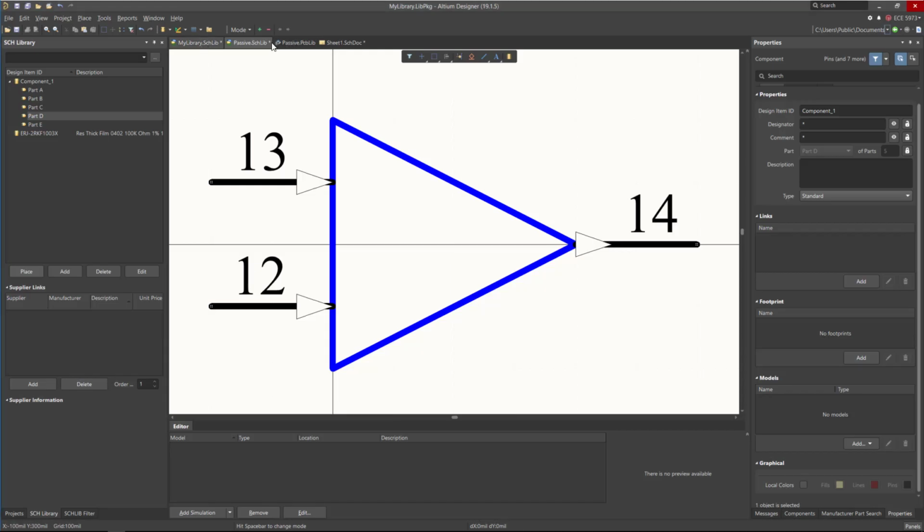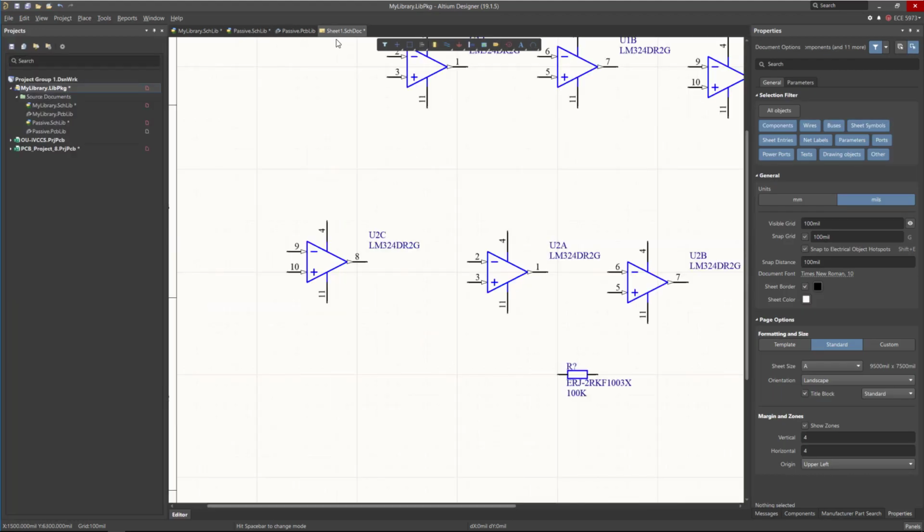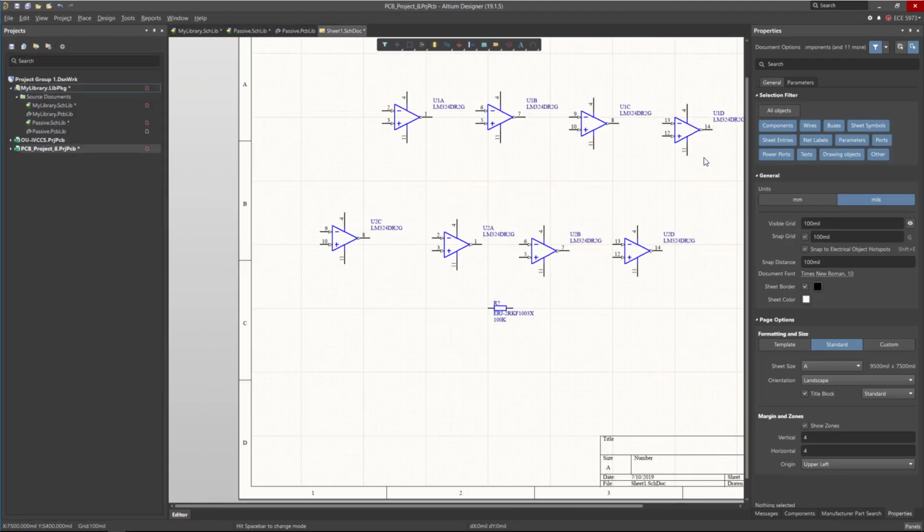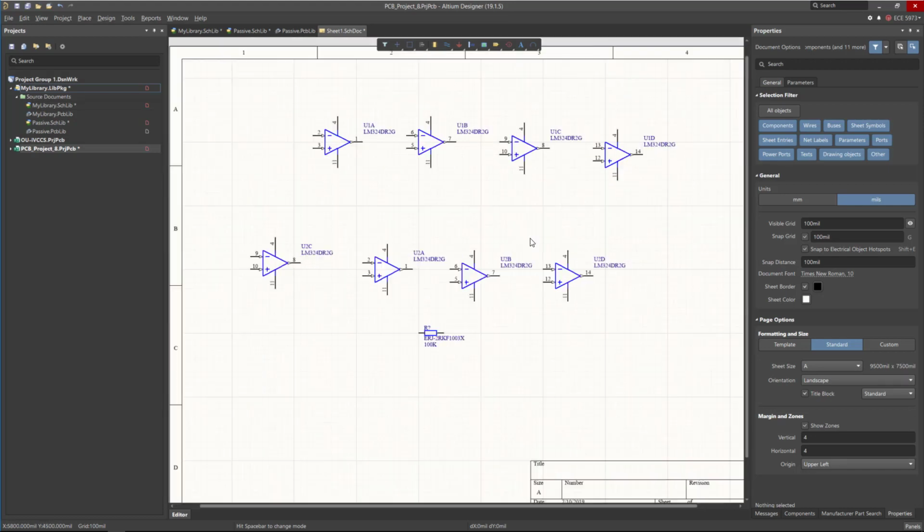Instead of doing what they did in this library, which is not recommended and not good practice, and I hate to see a library like that because it will give you a hard time when you do the electrical rule check. Now you need to connect every one of these to the power, and given that all of them are the same net, there is no reason for having all these on every single stage.